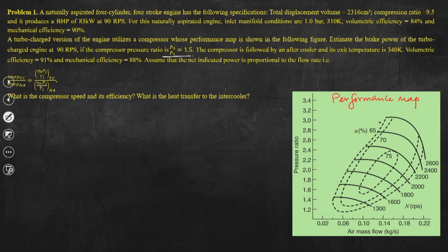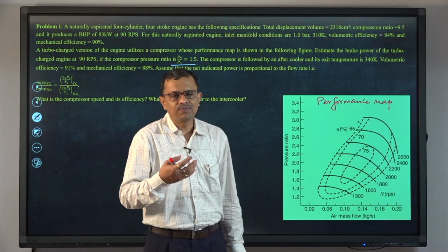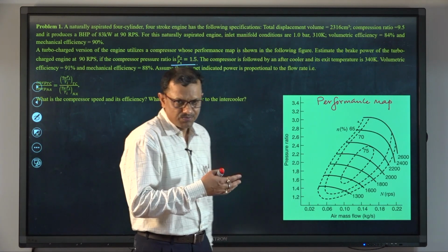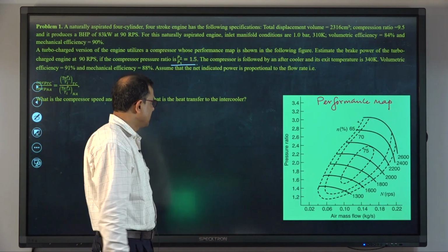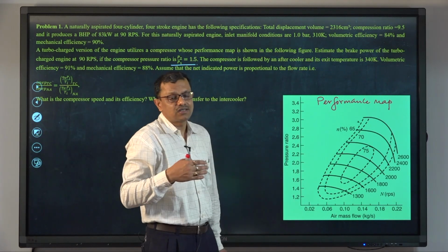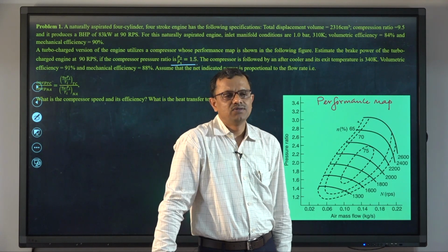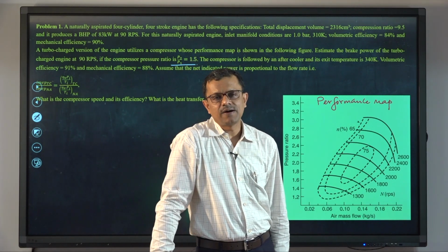The compressor is followed by an intercooler essentially to take off certain amount of heat or temperature of the compressed air, or otherwise it will lead to another problem, that is knock, because probably the engine is a SI engine. From the statement we can understand. It is not universal but true that aftercooler will not be there for the CI engines.